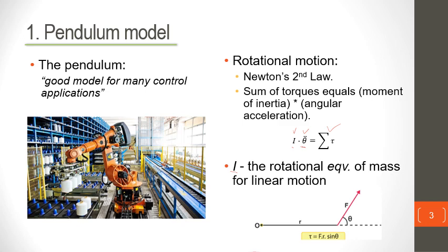Now, when we're talking about torque, we are simply talking about the turning force about a certain fulcrum. So if you have a force, say F, as illustrated here, and a link where the force is turning about the fulcrum, which is O, the turning force, when we talk about torque, is the component of this force that acts perpendicular to the link.